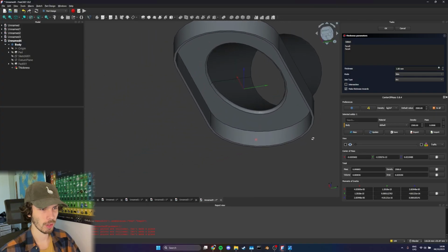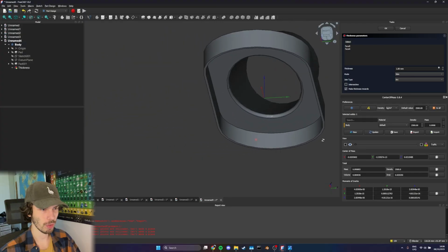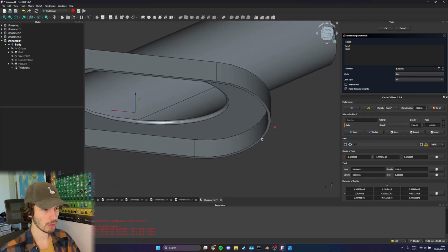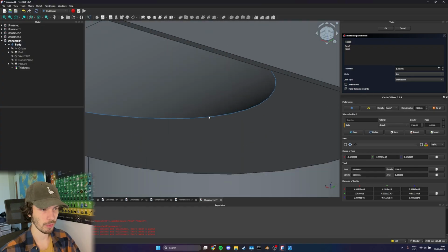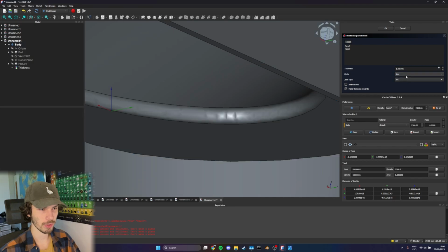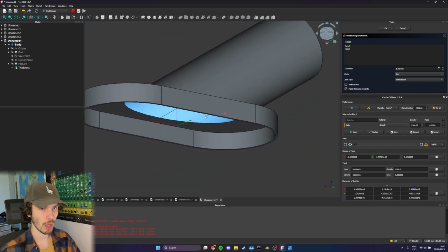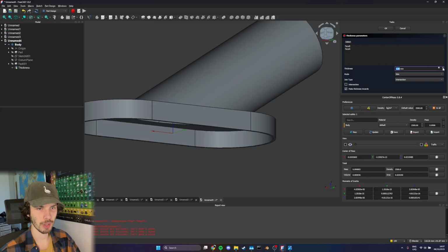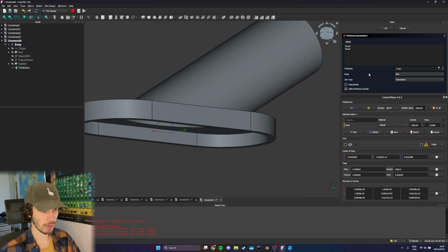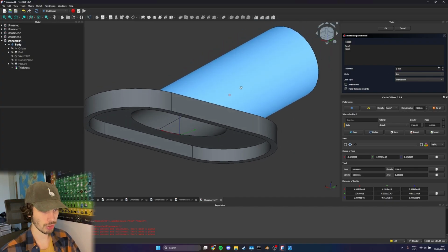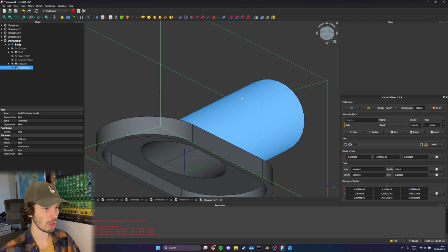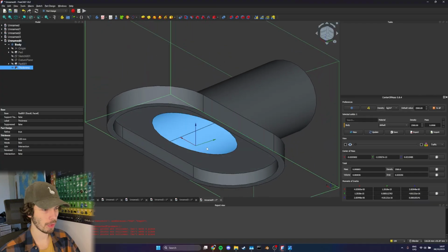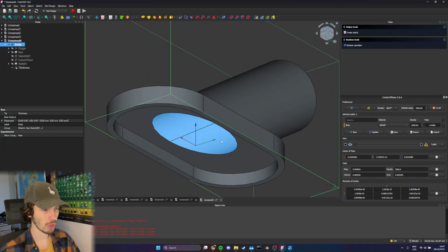And we can already see that it's doing a great job. We can see it through. And now we need to change the arc joint type to intersection. So the inner line over here would be sharp. You can see the difference over here. And let's increase the thickness to 3 millimeters as per the specifications of the drawing below. Let's click OK.